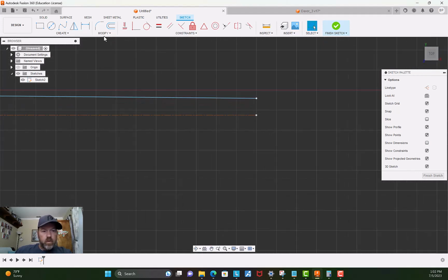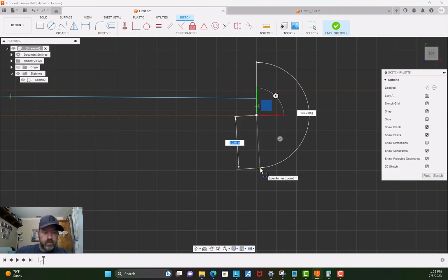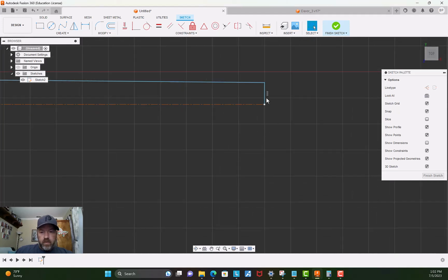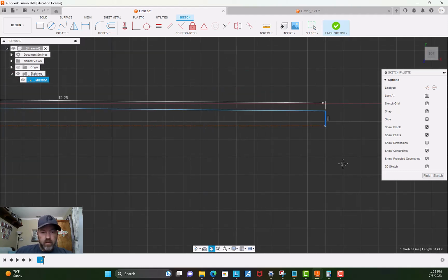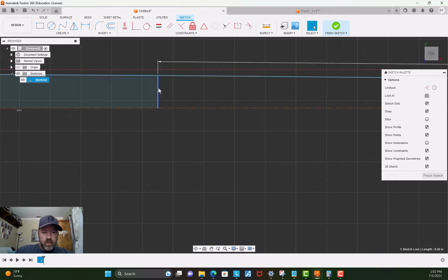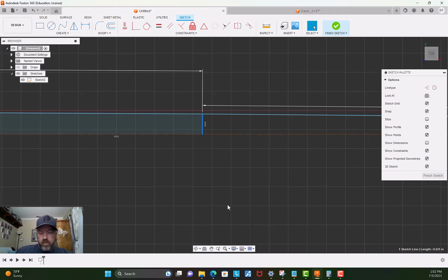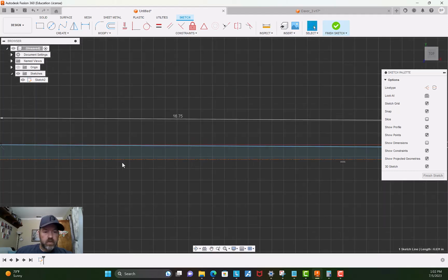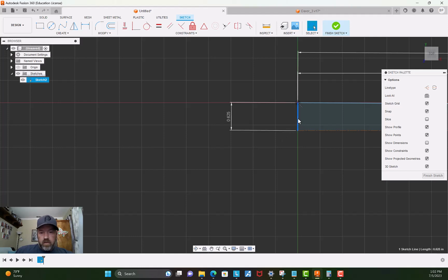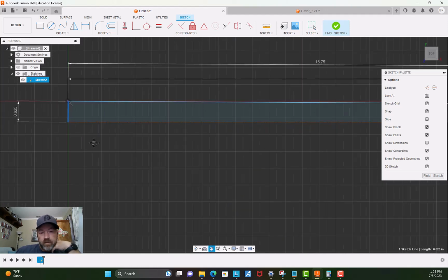And now let's close out this joint. So I'm going to come from here. Again, I want to make sure that my angle is 90, and I'm going to snap it here. And just to verify, if we click this one here, we can see the length is 0.420, which is half of 840. And if we do here, it is 0.531, which is half of 1.062. And here is 0.625, which is half of 1.25.